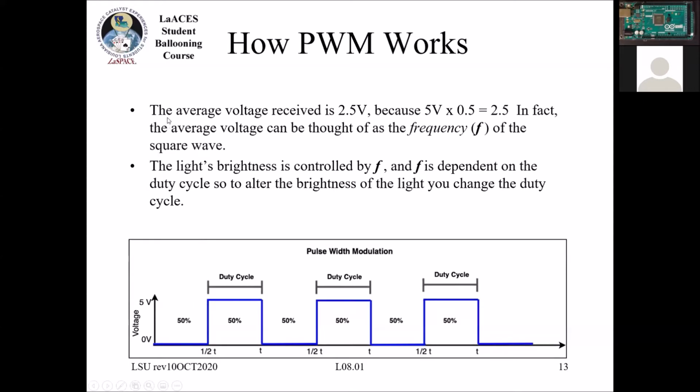So what you can do on the other end of this is basically have an averaging circuit that gives you an average output. So when this is at 50%, I would then average over that and get 2.5 volts. But I will point out, you need to have that circuitry that does that averaging, because this is still just a digital signal.